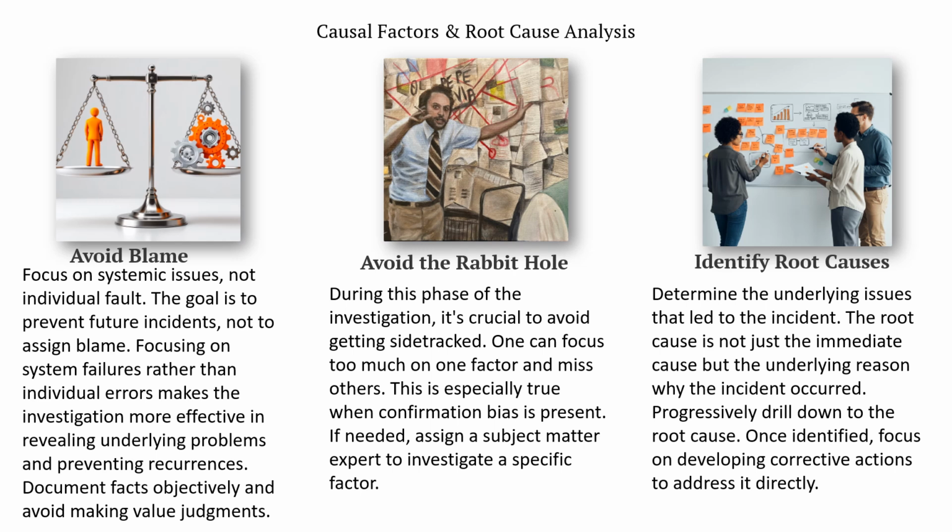Lastly, identify the root causes. Determine the underlying issues that led to the incident. The root cause is not just the immediate cause, but the underlying reason why the incident occurred. Progressively drill down to the root cause. Once identified, focus on developing corrective actions and address it directly.